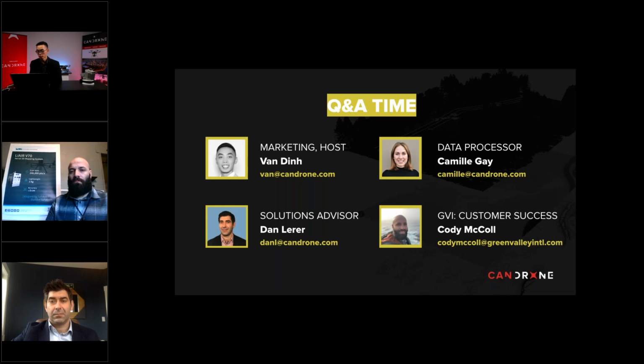Great, thank you, Camille, again. The next question is from Clarence. He's asking, does this classification process work with photogrammetry-based LAS or LAZ as well? And he saw that it did not require returns captured by the sensor. Yes, you can use an output from a photogrammetry model LAS and do this classification, no problem. It doesn't have to have an attribute referring to the return number. For your photogrammetry LAS point cloud, it will probably all say first return, or it won't have that attribute, but it won't matter.